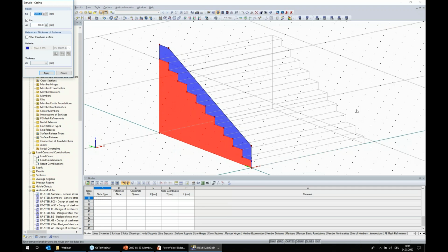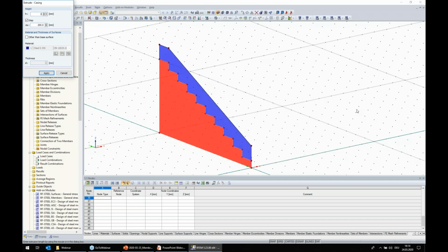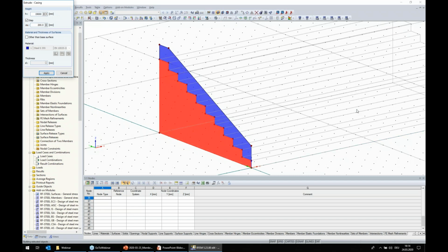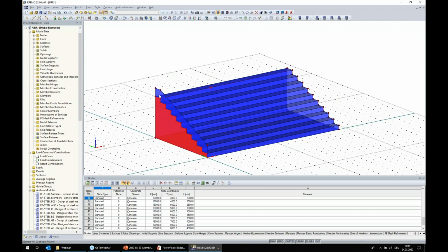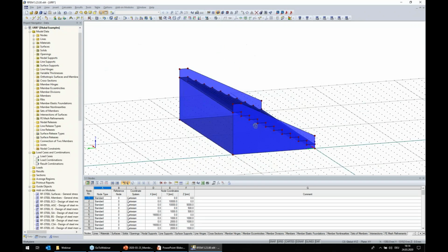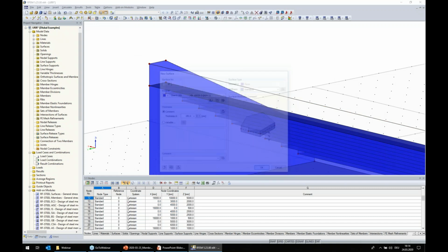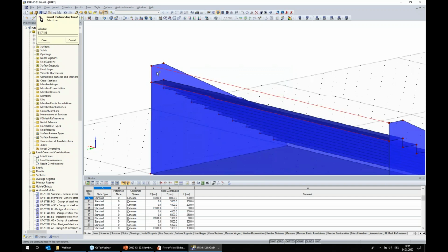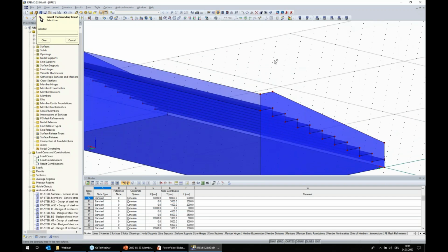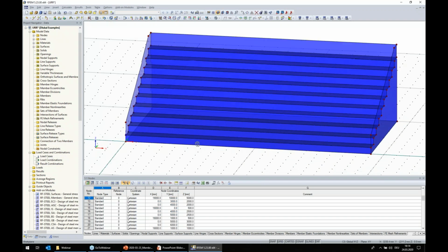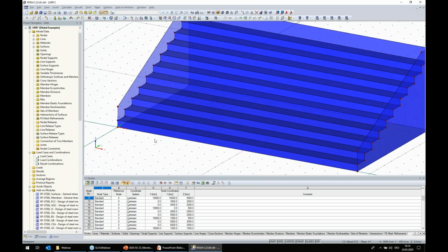Now we can take this cross section and copy it, or extrude it, as casing. You see, now we can give this surface a solid. We have a space of 20 meters, so we use 19 meters, return, and can close this casing by copying this covering on the other side. Now we close this body by producing this handrail on top and creating a balustrade surface again by picking all 4 lines around. And now we created with a few clicks, really a few clicks, a body for this wind simulation.